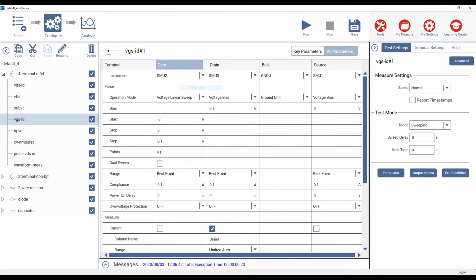So here we are in front of the semiconductor parameter analyzer, and you can see that this is basically a Windows PC with a highly integrated measurement interface. In this particular window that we're looking at, we're in the configuration mode where we get to define what our measurement looks like. And this software has already been told that we'll be testing a field effect transistor type of device.